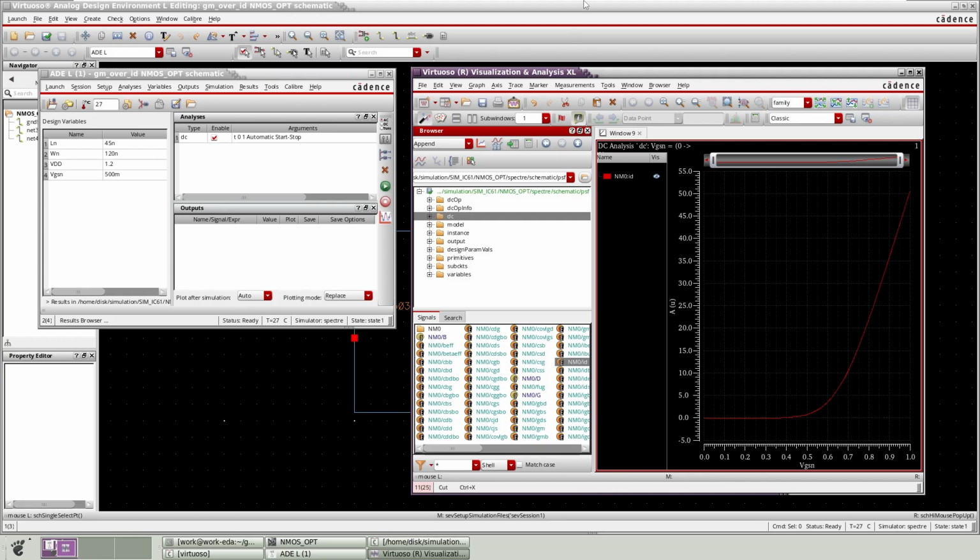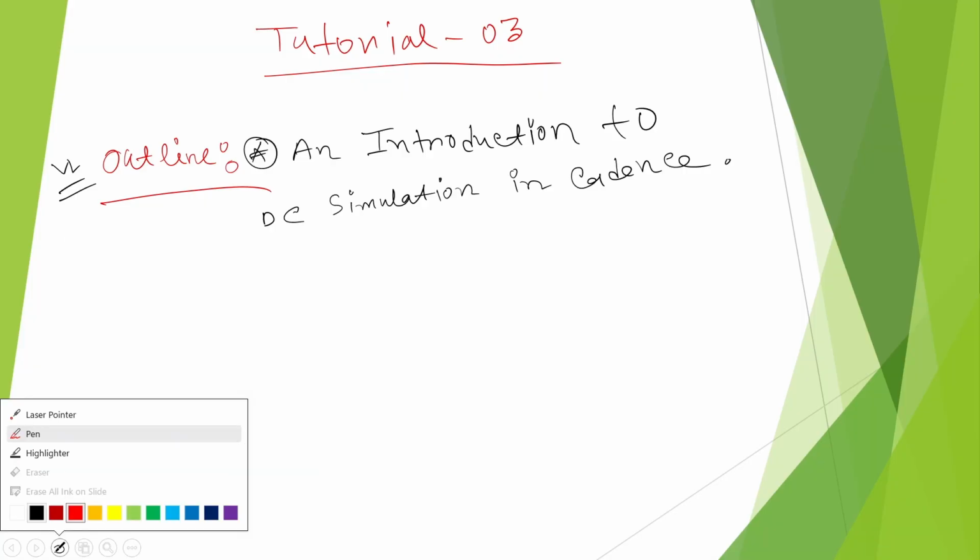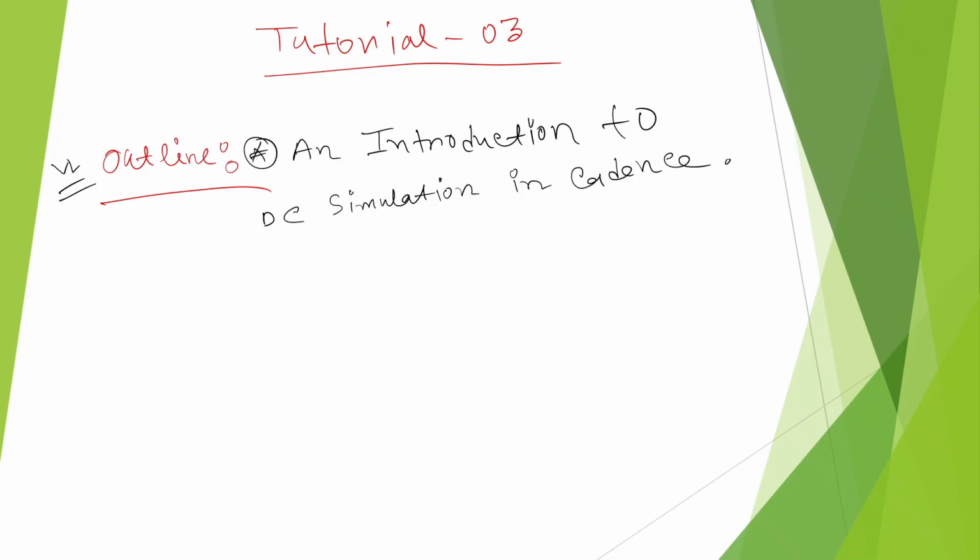So as you know from the previous tutorial video, we need some parameters. If you recall, which parameters do we actually need? In the previous tutorial video, I explained that by default the plot will be generated with respect to VGS because I sweep the VGS, and Y will be my different parameters. So this will be the default curve, and my parameters are ID,